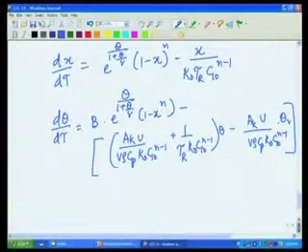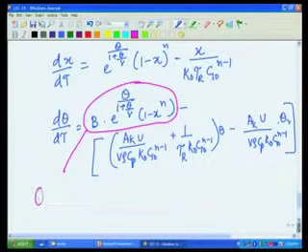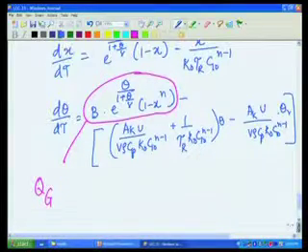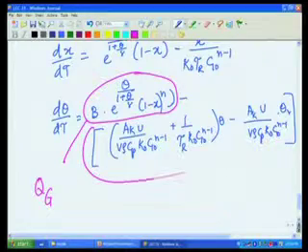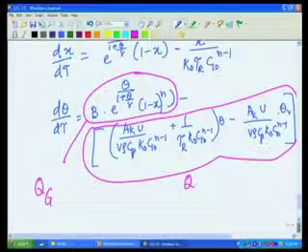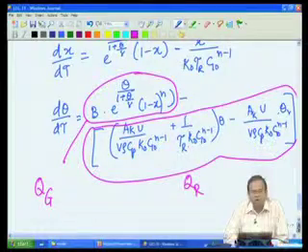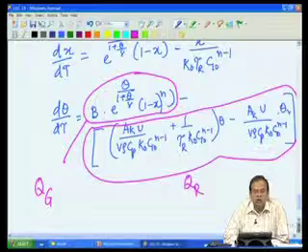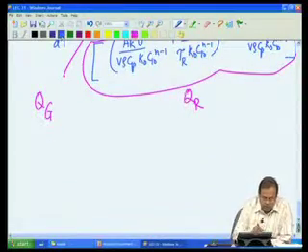Okay. But what is interesting to once again realize is that our energy balance is once again a balance between heat generation rate, which is actually the same term as what we had before, and the heat removal term, which is slightly more complicated than before, but it has the same essence of representing how much energy is being removed from the system. There are two terms here, and this one is obviously coming from the heat exchange or heat removal due to the jacketed fluid, whereas this term is arising because of heat removal due to the change in the enthalpy of the system. So, convective energy removal.